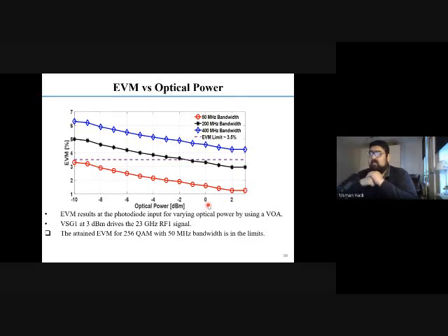So here you can see that still without linearization, for 50 megahertz you don't need linearization, and we can see that the 3.5% limit is already met here, and you're good to go. But then if you have 400 megahertz, you are not meeting the criteria of the 3.5%, and partially 200 megahertz bandwidth is also not meeting the criteria. So if you have to use 400 megahertz bandwidth, and as 5G is evolving, the higher the bandwidth, the higher the utilization will be. So it is true that for 400 megahertz bandwidth, these results are not meeting the standardization.